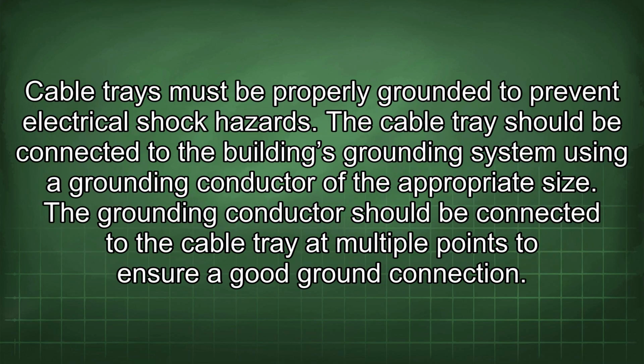Cable trays must be properly grounded to prevent electrical shock hazards. The cable tray should be connected to the building's grounding system using a grounding conductor of the appropriate size. The grounding conductor should be connected to the cable tray at multiple points to ensure a good ground connection.